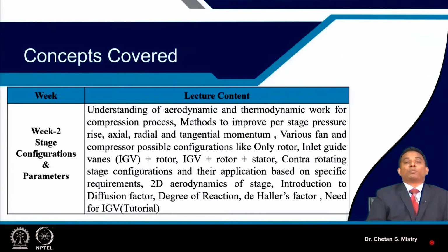Then we have introduced the parameter degree of reaction, and that is an equally important parameter. It gives us an idea whether the diffusion is happening in our rotor, or only in the stator, or in both rotor and stator. So based on that, we will be doing our calculation for the design of degree of reaction. We have discussed that it is the thermodynamic measure of your diffusion process.